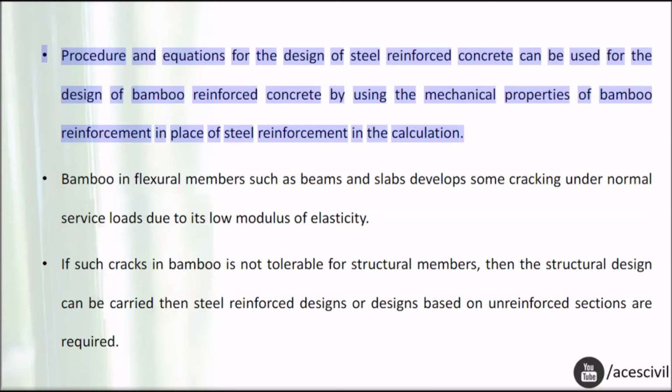Procedure and equations for the design of steel reinforced concrete can be used for the design of bamboo reinforced concrete by using the mechanical properties of bamboo reinforcement in place of steel reinforcement in the calculation.